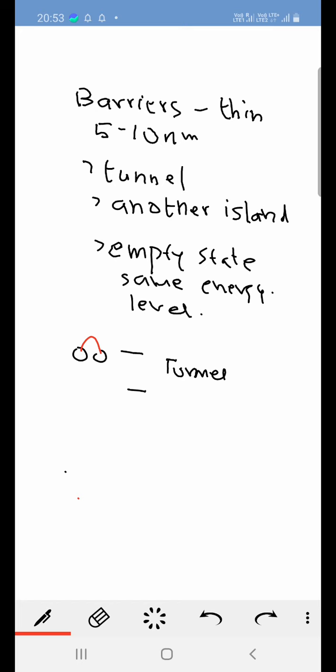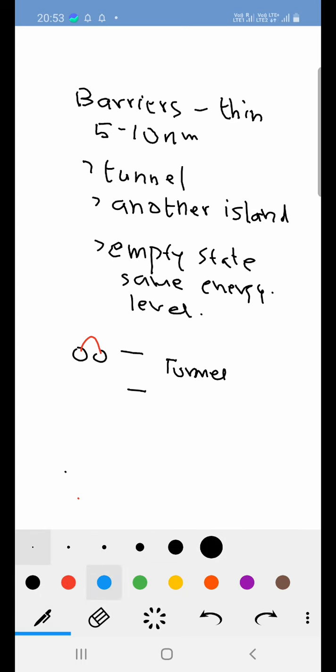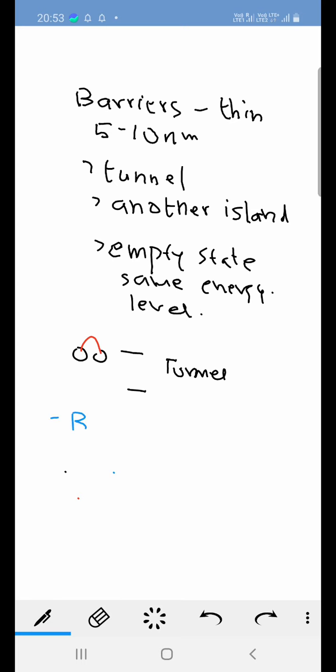Now, these two effects of energy quantization and tunneling strongly influence the flow of electrons through the single electron device. Now, the question is when a bias voltage is applied across the island. It induces mobile electrons in the conduction band of the source region to attempt to move through the potential well in the island region to get to the region of lower potential in the drain.